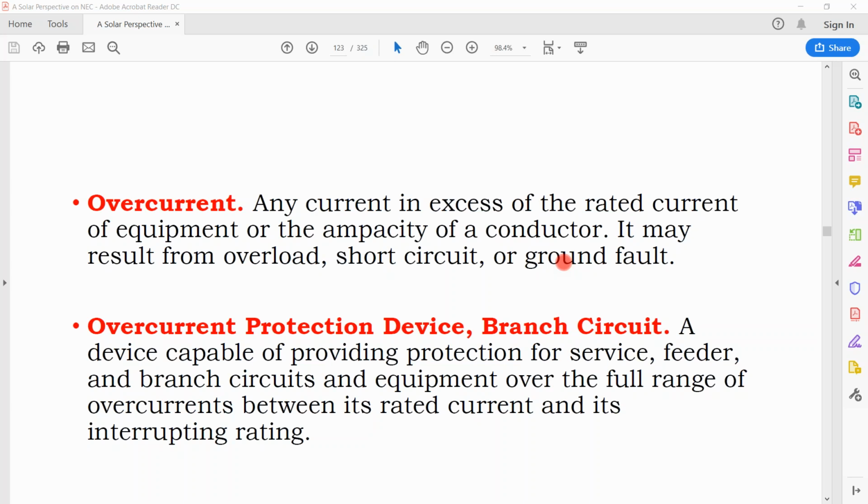So they did all their calculations at 90°C and then used a box that's only rated for 75°C, and then didn't go back and say, okay, what's the temperature going to be at 75°C so that I apply my correction factors appropriately. That results in an undersized conductor,